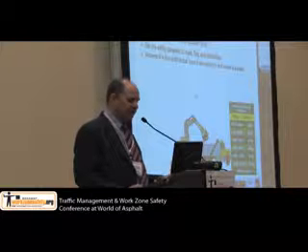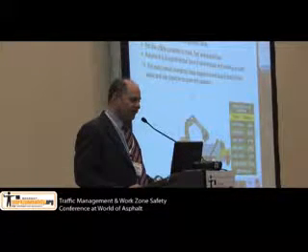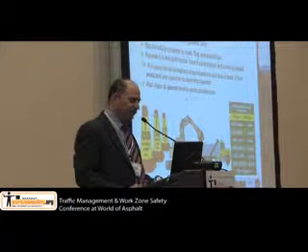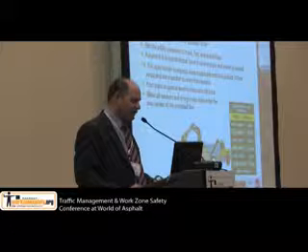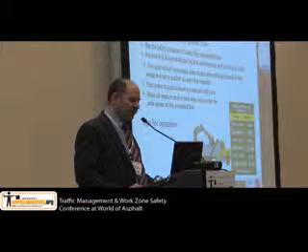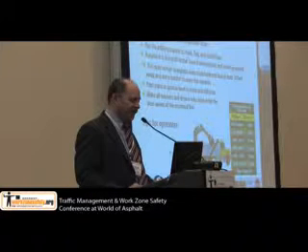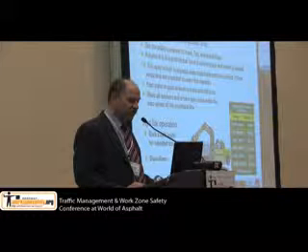You should assume that it's live until it's been tested. Have it de-energized if possible. If it is energized, keep equipment and loads at least 10 feet away and post signs at the ground level to mark safe distances. Make all the workers and drivers who are entering the area aware of the overhead power line, and have the operators have a safe route for travel and make sure that they drive slowly.